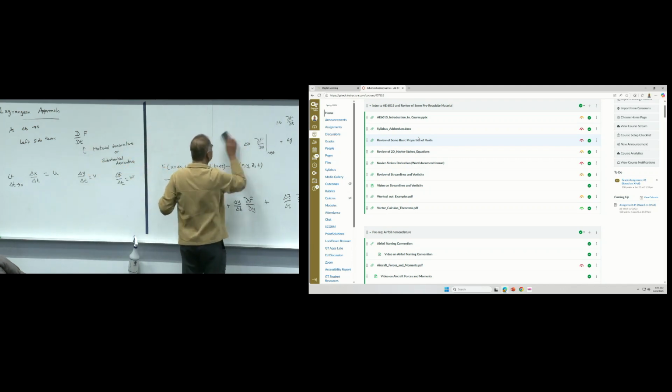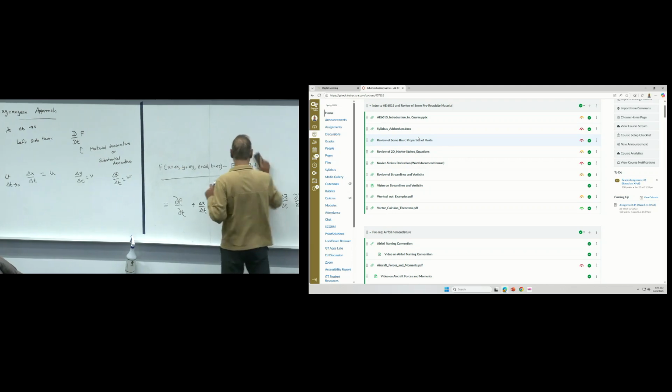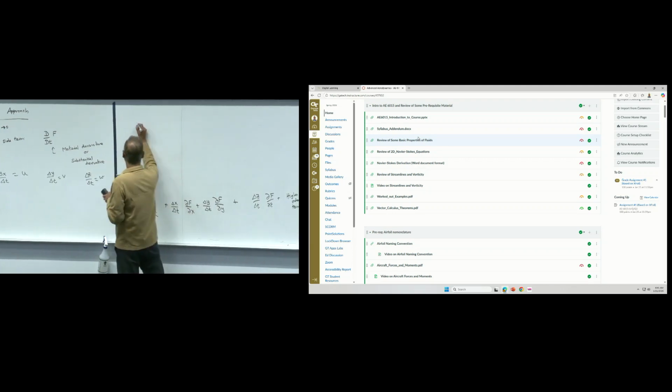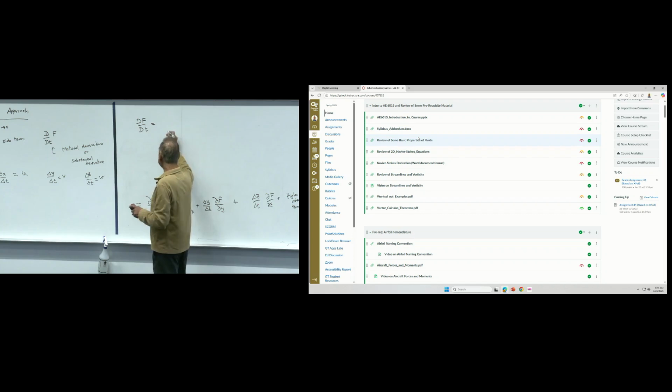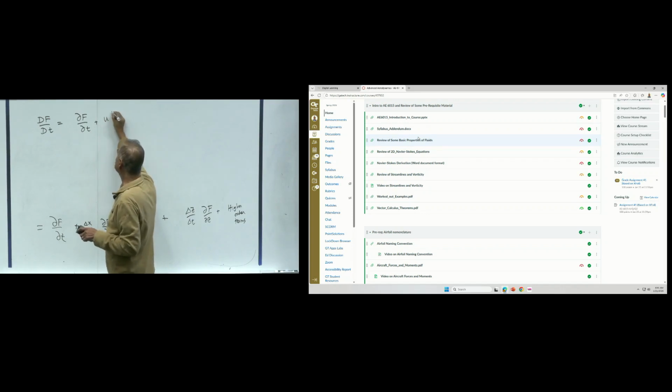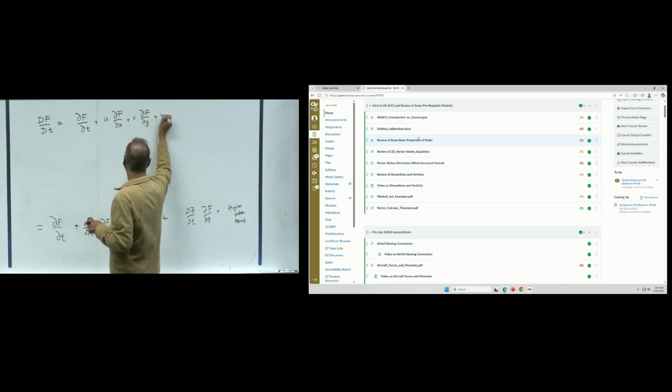So what we will get is, Eulerian coordinate system, Lagrangian coordinate system derivative, which is the material derivative, would be Df/Dt equal to the partial derivative ∂f/∂t plus u times ∂f/∂x, v times ∂f/∂y plus w times ∂f/∂z.